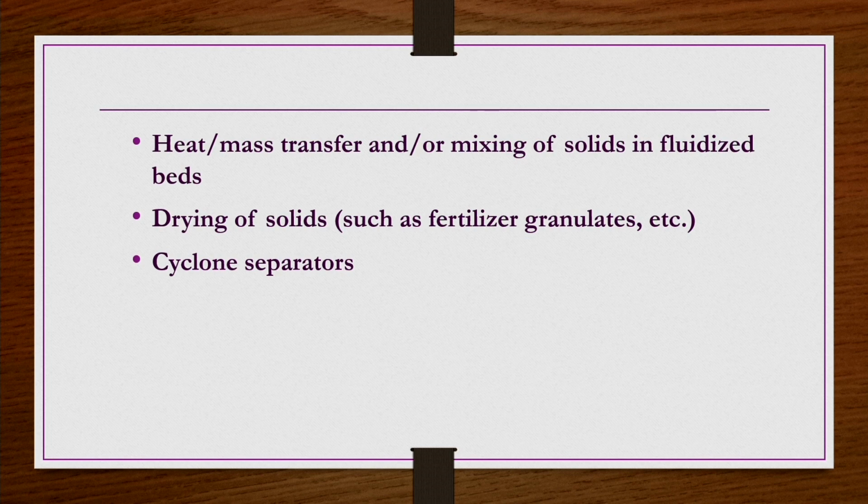So, you apply the cyclone separator and collect those particles, and the remaining effluents, if they are not environmentally dangerous, you can leave into the environment. Otherwise, after separating the particles, those gases should be collected into bag houses, etc., and proper disposal has to be done.